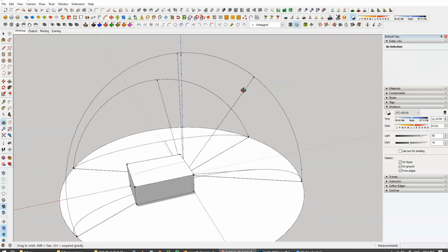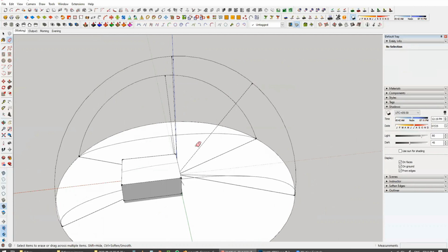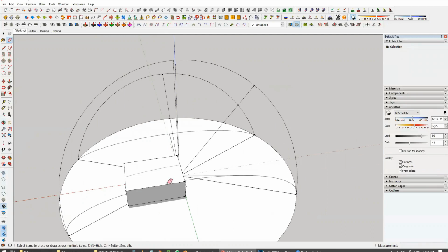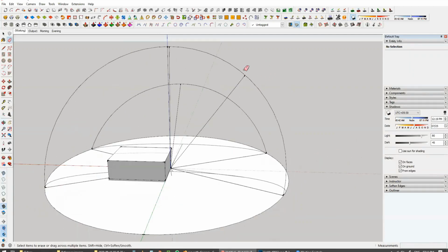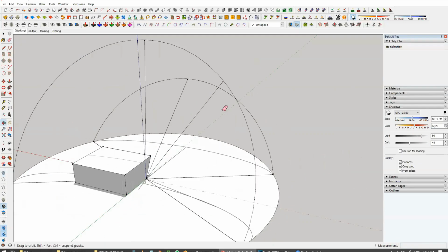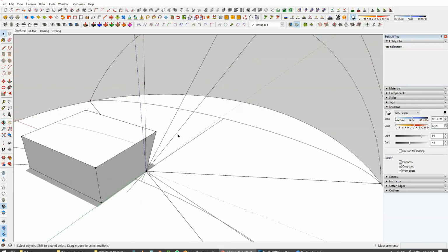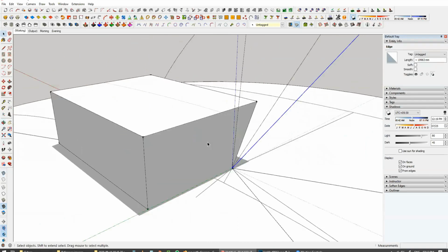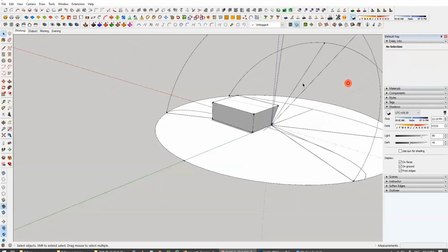the basic concept is you can get the angle from the sun path diagram if we have the shadow direction, and you can find out the angle of the sun as well, and you will also find the altitude of the sun because we already have the path, right? So once we have that angle, you can design it for this angle of the sun, right? So let's say we have to prevent the sun for this angle.